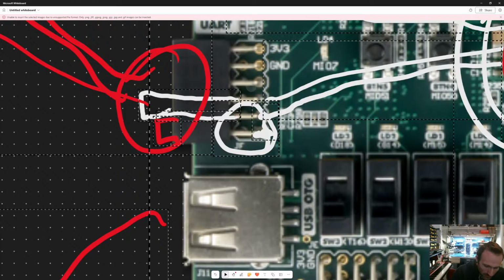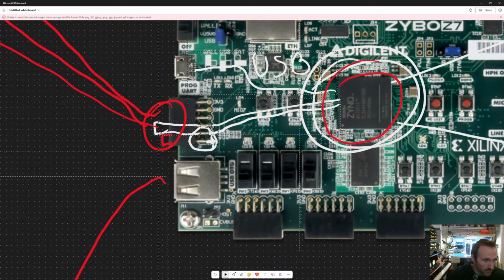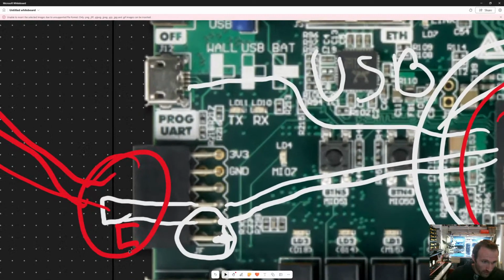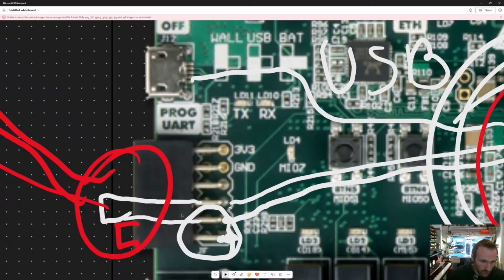The loopback was supposed to be here, on the white line basically that I have. The loopback signals were sent on the white line. Sorry, the MOSI and MISO signals were going to these two pins. They were being routed to those two pins. But I had a jumper on these two pins. So how is it even possible that I was getting back somewhat correct data?